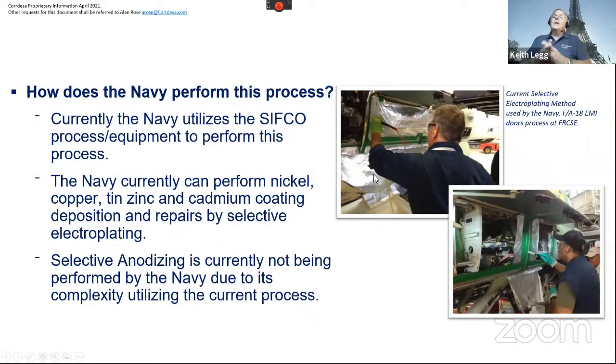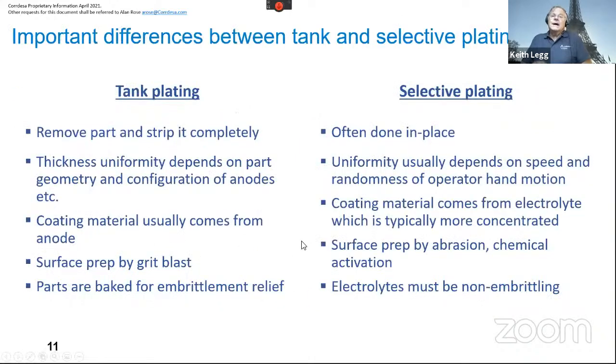So you have to put up all kinds of barriers and channels and catchments, with aluminum foil. We've seen people doing this. It takes them hours to prepare a plane to do this kind of thing. So the issue there is, wouldn't it be much better if you didn't have this stuff flowing everywhere? Well, you can, and for that reason, people have now come up with what we call non-drip brush plating and anodizing.